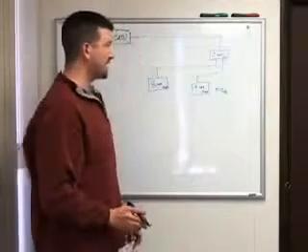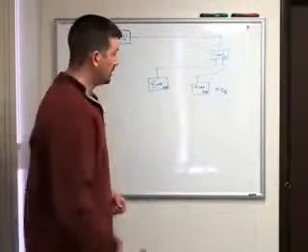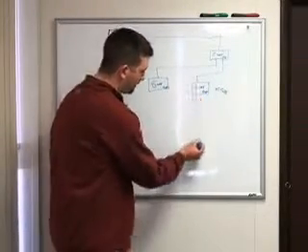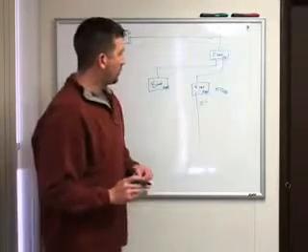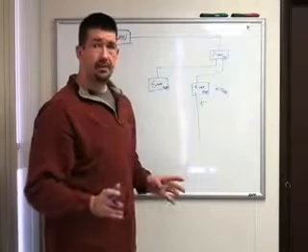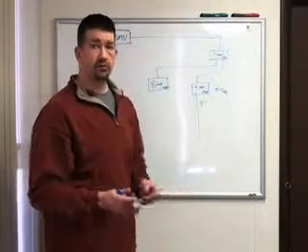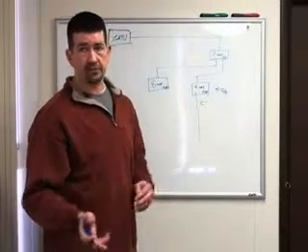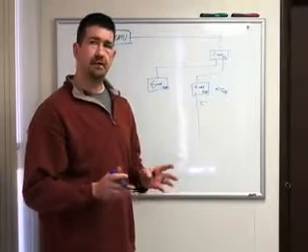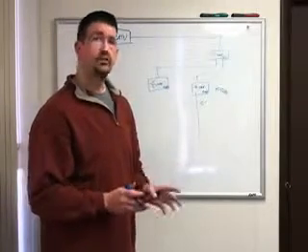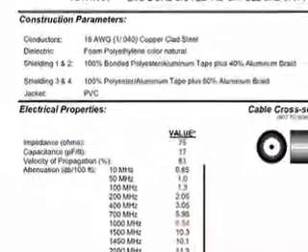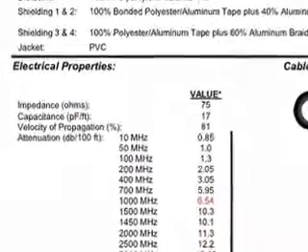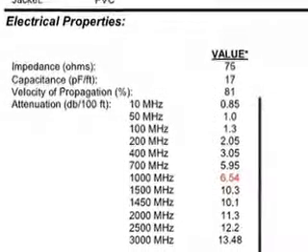Now the next thing we have to calculate on this is the wire. Let's say that the wire coming off our splitters here is 75 feet. RG6 is different depending on whose wire you're using or who the manufacturer is, which model they're using. They all have different losses on them. You need to look at the manufacturer spec sheet, and they will have a section there which shows you over 100 feet how much loss there is at 1,000 megahertz.